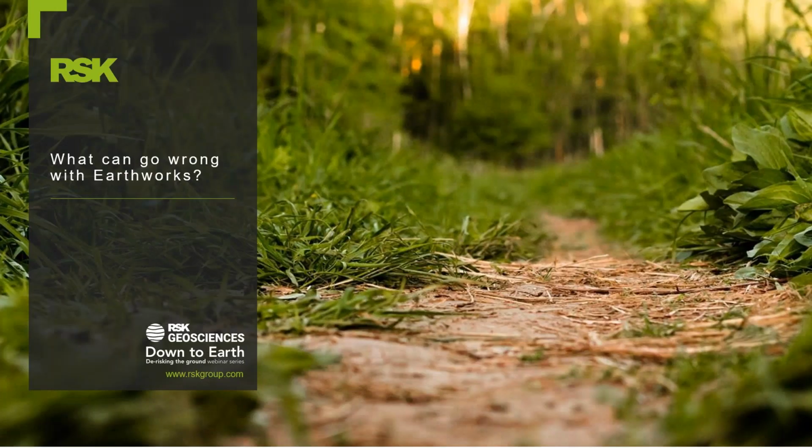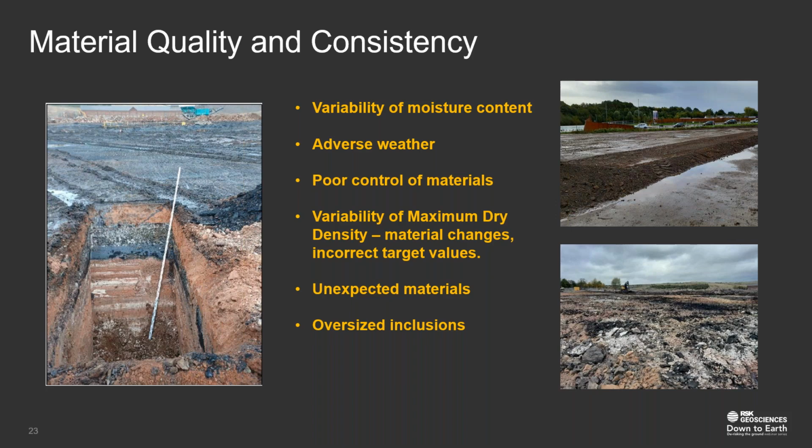Okay, so what can go wrong with earthworks? Quite a lot, unfortunately. I suppose probably the biggest issue is the fact that you're dealing with soils and that soils are variable. They're not consistent. Even natural soils will vary a bit. That's why you really need to take several optimum moisture content maximum dry density tests and use an average to arrive at a target value.